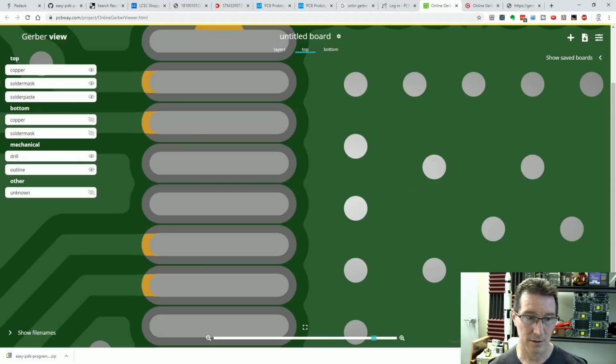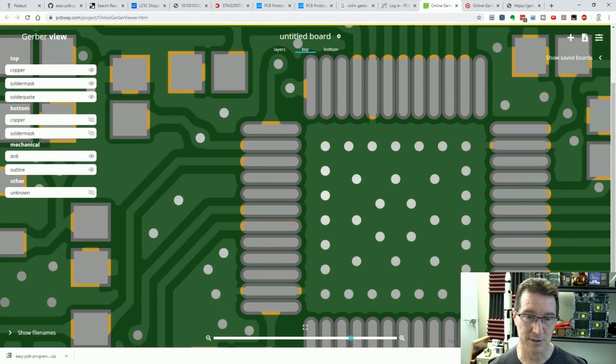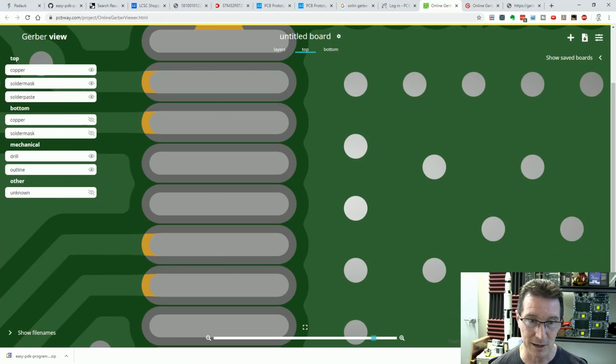I like that. Oh yeah, nice. Anyway, you can see the solder mask sliver there. The expansion is quite large. I think my board had more sliver than that. Have they automatically expanded that? You can see the line going between the pads. I mean, that won't be manufacturable, right? I guarantee you, that looks like a couple of thou, a couple of mil, a couple of thousandths of an inch thickness. That's just not going to get manufactured.